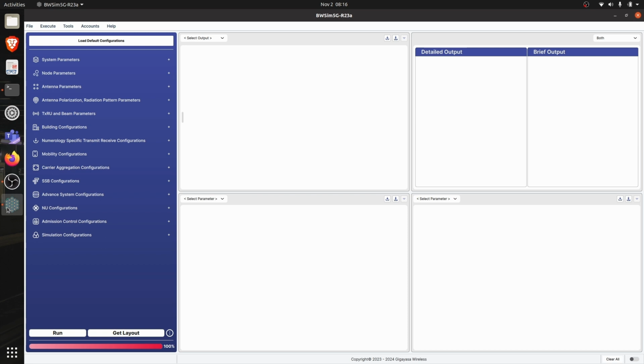Due to the high SNR, high data rate communication can be facilitated between transmitter and receiver in these LOS links. Some of the applications which were not possible in earlier generations of wireless communication and are now possible in 5G, due to its massive number of antennas and huge bandwidth, millimeter wave bandwidth, are like positioning. These applications require the presence of a LOS link. Take positioning for example. It involves the estimation of angle and time. In non-line of sight links, there is a bias in these calculations, thereby deteriorating the entire process of positioning. However, in the presence of LOS, you could get accurate positioning results.